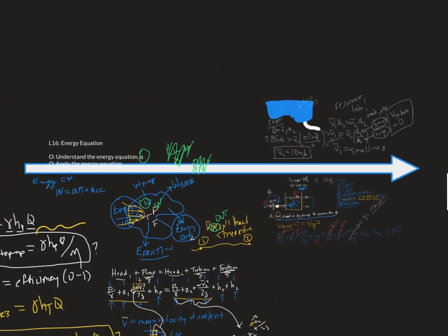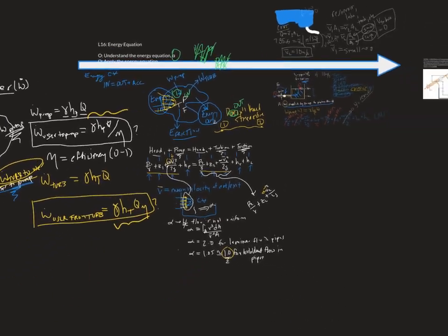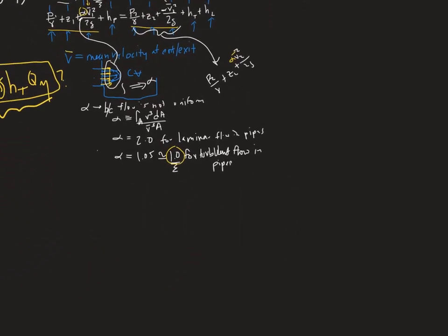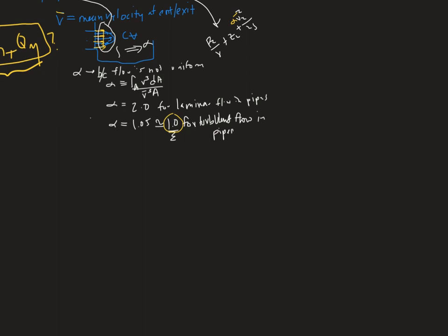So we know from my notes earlier, if we go over here, we'll just deal with it down here. It's going to depend on whether or not the flow is laminar or turbulent. So we need to figure that out. Laminar versus turbulent is based on the Reynolds number, V times the diameter of the pipe divided by nu. That's a nu, not a V.